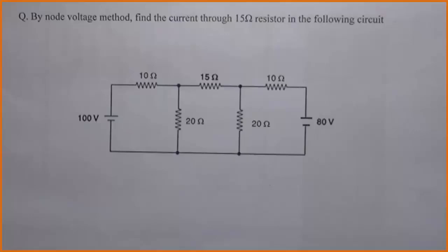Today we will study about node voltage method, or it is also called as node analysis. In this method, we are considering node voltages in the given circuit. This method is based on Kirchhoff's current law, that is KCL, and the method is useful for calculating voltages or potentials at different nodes in the circuit.